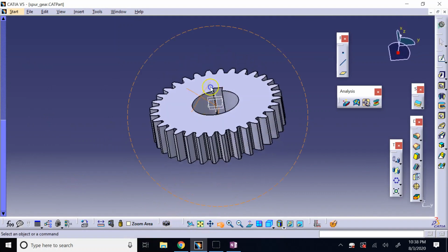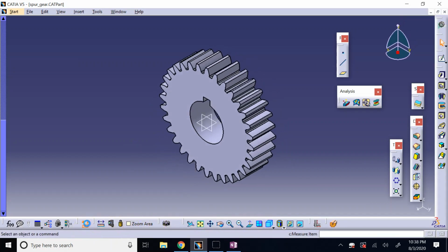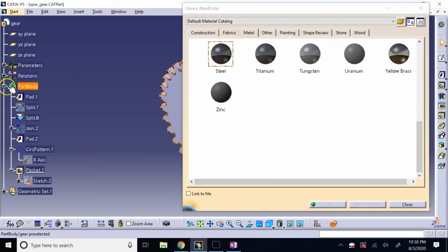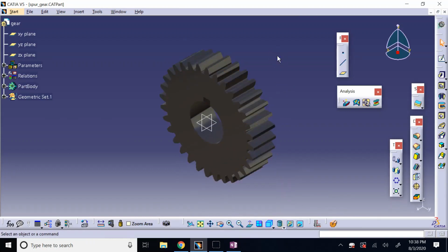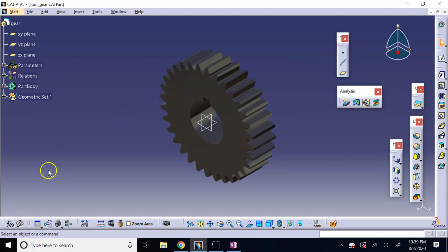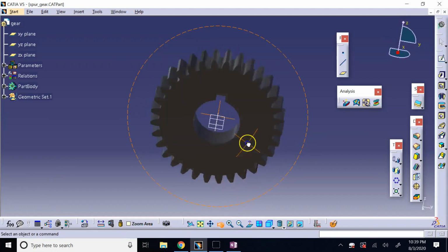Okay, so this is how a gear is. The shaft will go here, and then on the shaft there will be another keyway like this, and then they match each other, and then the key will come here and match them together. Okay, just as a final thing, let's just make it look nice, and we can finish it up. So here is your steel gear, spur gear with the hub and keyway and everything. And you can, of course, convert it to a helical one later according to the last 2 pages of the tutorial. So hopefully that gave you enough of info about how difficult it is to make a gear properly and what parameters are involved in creating it. Thank you.